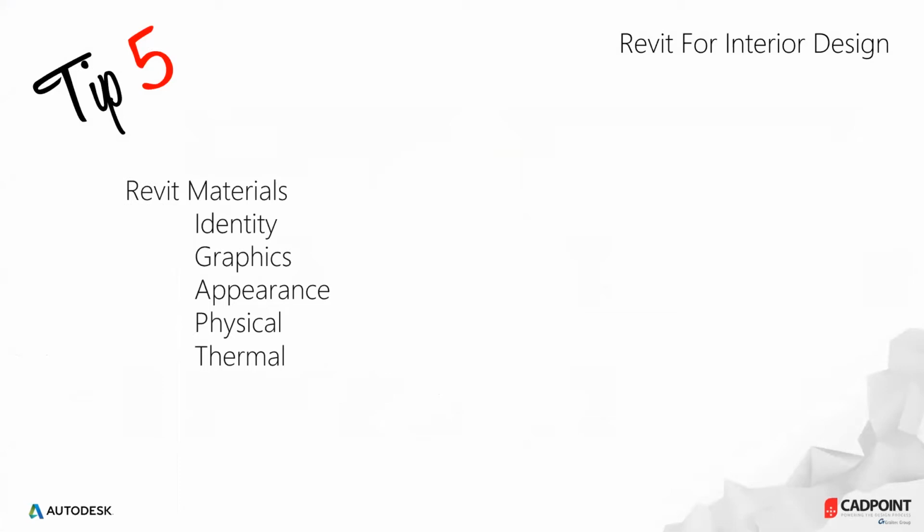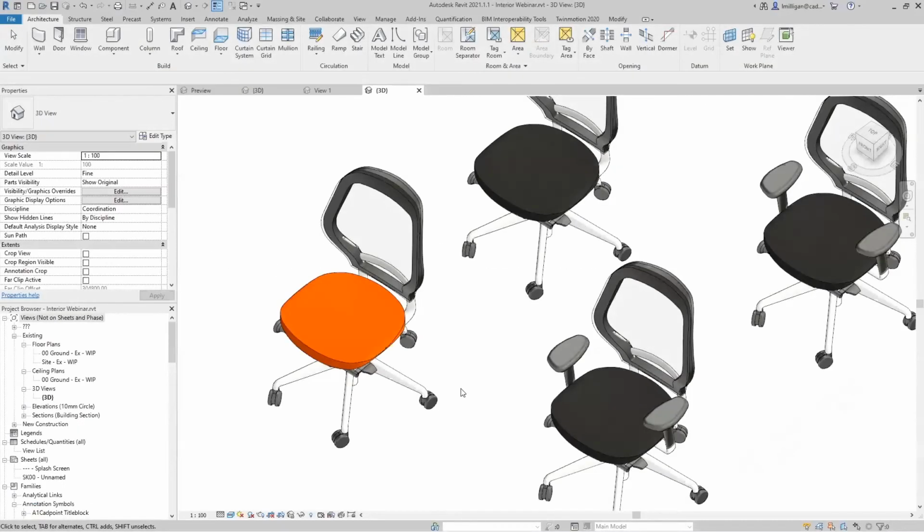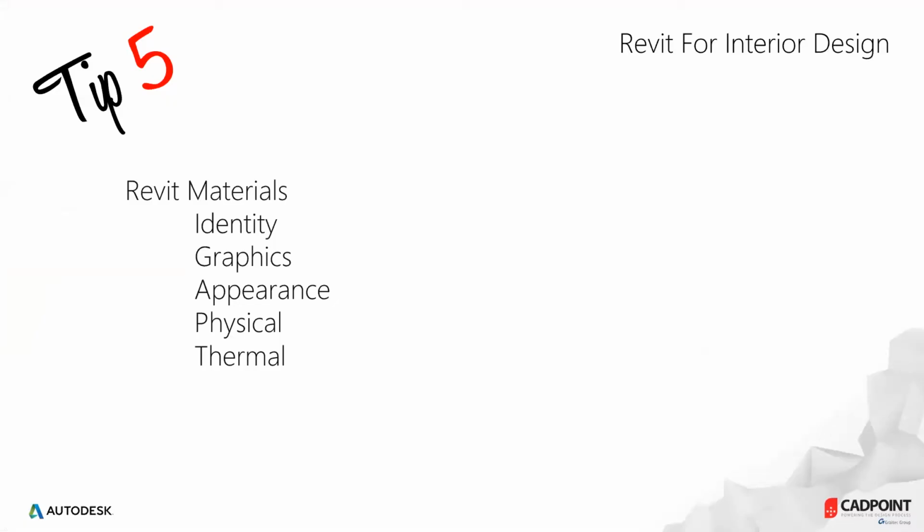Okay, so tip 5 is to do with Revit materials. In Revit, materials are more than just how an object renders. A material is a grouping together of settings. Autodesk actually call these settings assets in Revit. These assets are the identity, the information about a material; the graphics, how an object will look graphically, i.e. in plan, elevation, section, and non-rendered 3D views; the appearance, the render appearance of an object, how it will render; physical, so structural properties of an object; or thermal, and the thermal properties of an object.